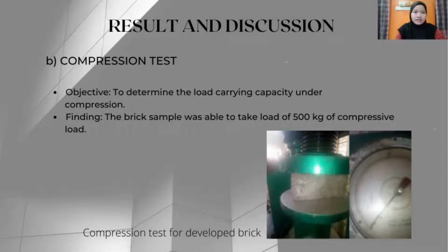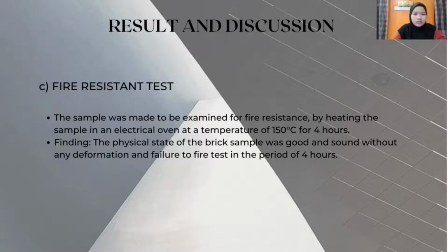And then the second test is the compression test. The objective of the compression test is to determine the load carrying capacity under compression. Based on this compression test, the result shows that the brick sample was able to take a compressive load of 500 kg.